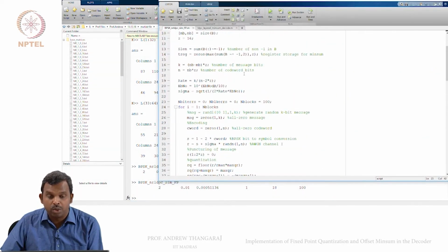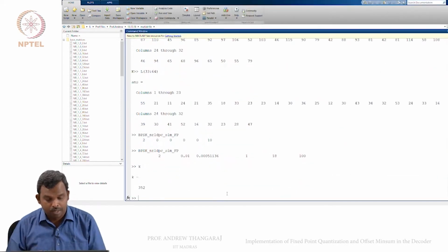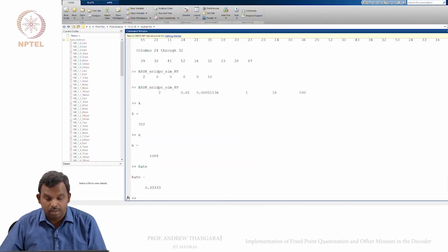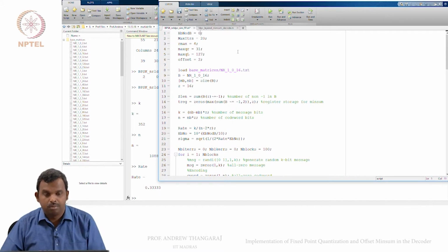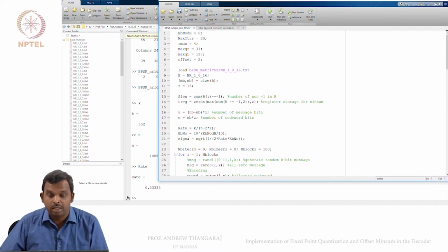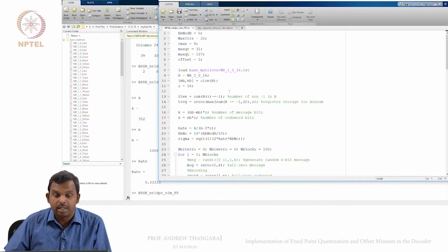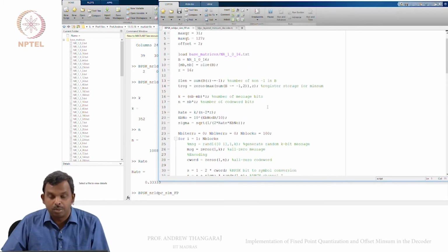You can even reduce the Eb/N0 if you like. Remember, this is just a block length of 1000. So if you look at K, N is just 1000, rate will be 1/3. Okay, so because I did that, and so this is easy enough to do. You can even reduce the Eb/N0 further, and so you'll see more errors will start creeping in. So at this point it was just 10 power minus 2, 1 out of 100 were an error. If you go to 0 dB, you will get more errors at these block lengths, but the whole decoder is working sort of reasonably.